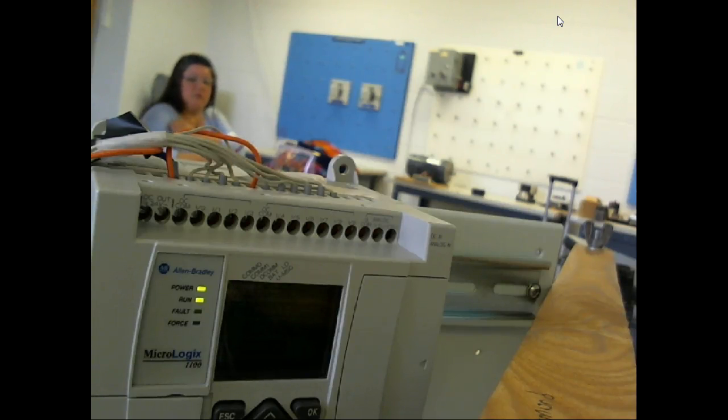You run inputs. And then what you need to do is figure out, okay, is this within the range of how much current these inputs can handle? So the more solid state inputs that you have to run, these guys have to be powered up, right? You could run thousands of switches off that power supply because a switch or a contact requires no current. But as soon as you hook up a solid state relay, those guys most of the time have to be powered. They take 3 wires. So what we do is we usually run those off an external power supply.